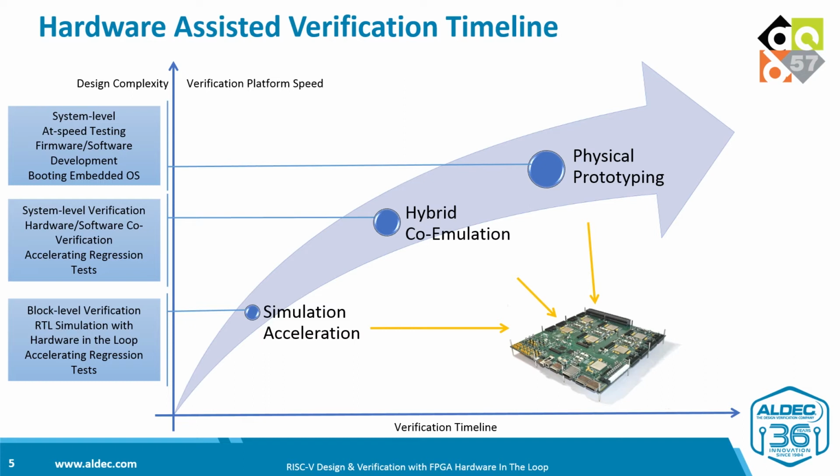So, summarizing, hardware-assisted verification is a significant improvement of the traditional simulation-based verification process. It allows to sign off the chip with higher confidence and significantly shortens the bring-up process when the first chip production samples arrive to the lab.